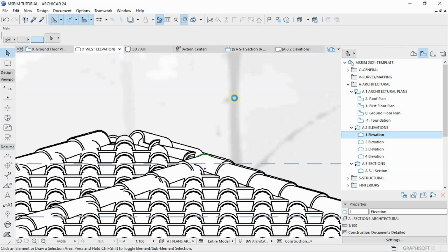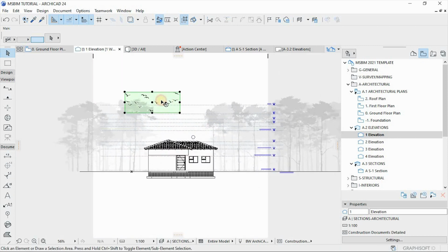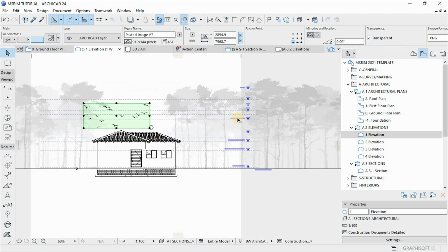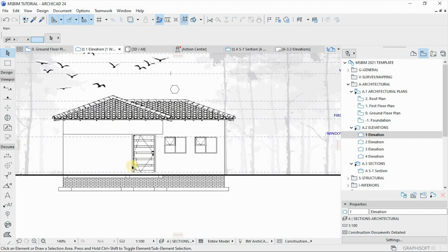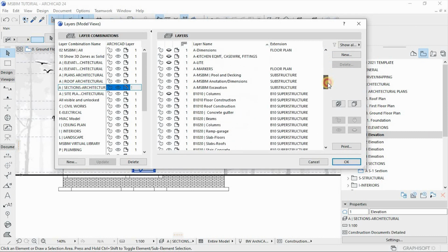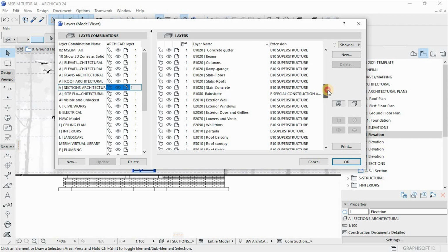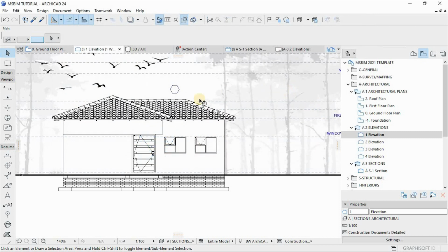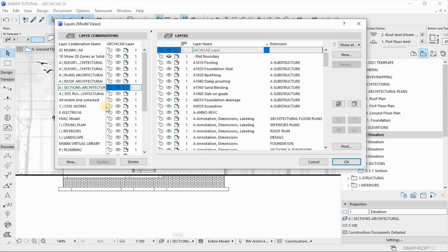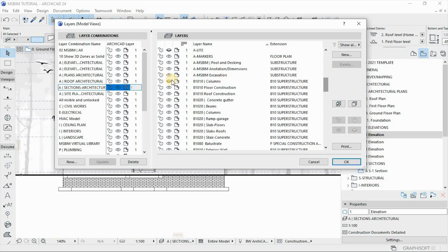If you check your elevations as well, you do the same thing. You're going to have the same information available there for you to just adjust, and then bring the beds a little bit closer to the drawing. Here we have a layer that is off, which is for columns. So Control A, Control L, and then go to superstructure. Where are the columns? It's active. It's supposed to have our columns there. Sections. What happened to our column? There we go.